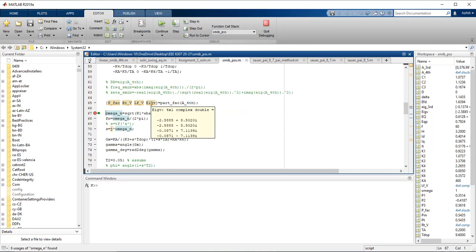Which set should be the dominant eigenvalue from this list? Which complex set should be the dominant or critical eigenvalue? So minus 0.0871. Yes, excellent. So minus 0.0871, because they are nearer to the y-axis in the S-plane. But we only know this, and still we don't know with which state that pair of complex eigenvalues is linked more. Okay, so now we look into the participation.